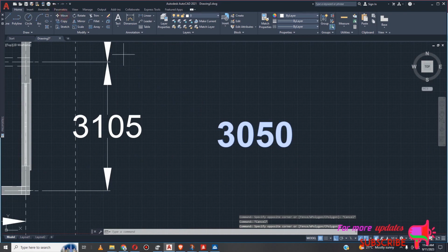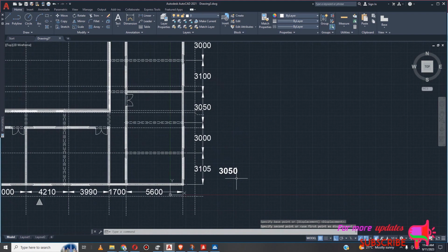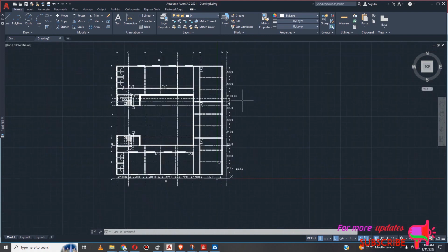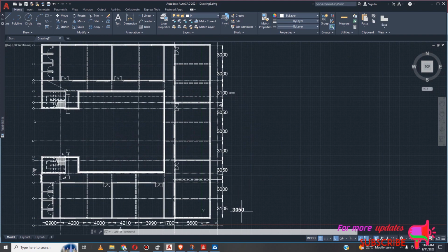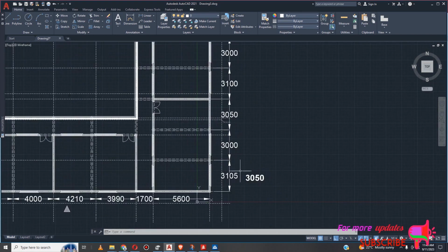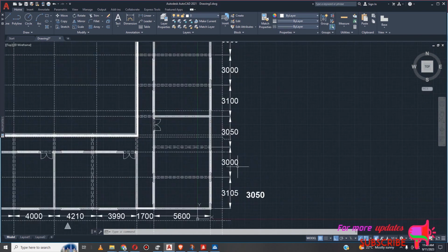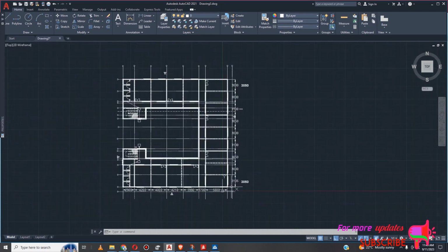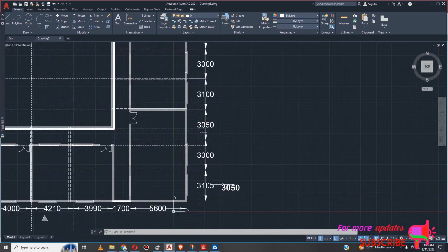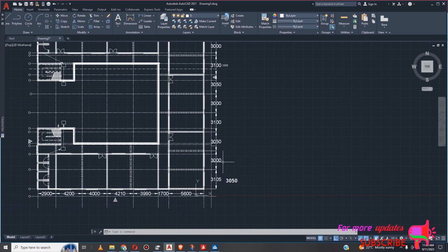So I will try as much to get that symmetry, so that when I work, I'll be sure I'm within the limited provided area. So this length should be similar to the one up there, but you can see I have not increased or reduced because I have just subtracted 50 from this, that 100, and added to the other one at the top. So at the end of the day, the total is just same, maybe just a very small difference. So that is what I'm basically trying to do here before I start modeling this half model in STAAD.Pro.